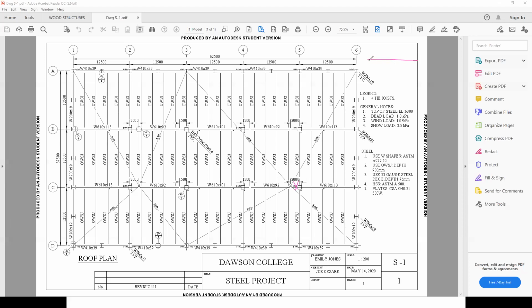You want the top of that joist to be at, like in her case, or I think it's a she, yeah, Emily, you want it to be at 500. You wanted the top of the joist to be there, and you know that this joist has a shoe of 100, so she should have put minus 600 here. Okay, so that it's the joist that happens to be at the right height, and that was a mistake. So that's a mistake. And of course, that's a mistake also, and they're all wrong. So therefore, she probably lost a couple of marks for that.